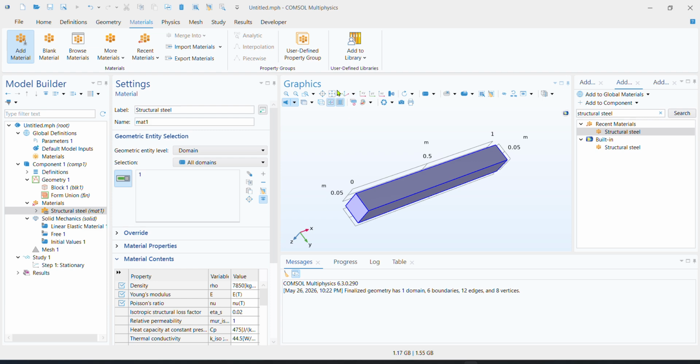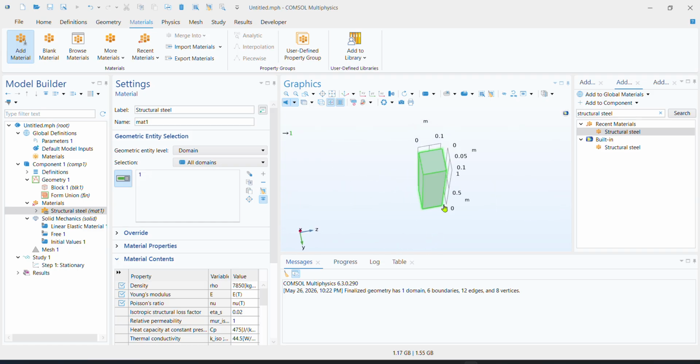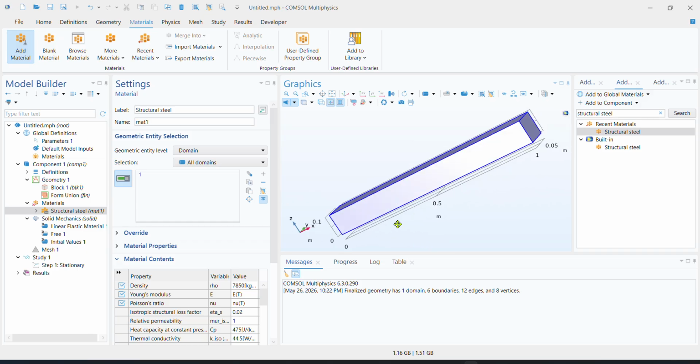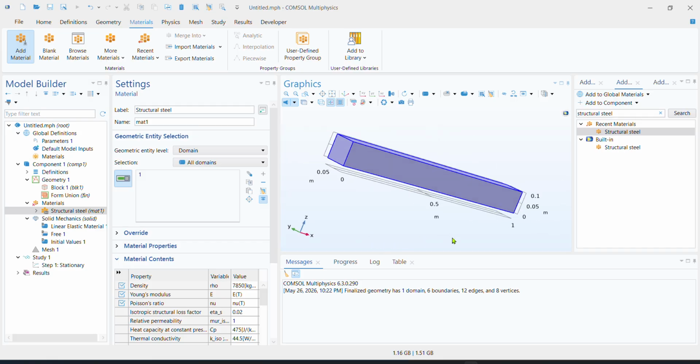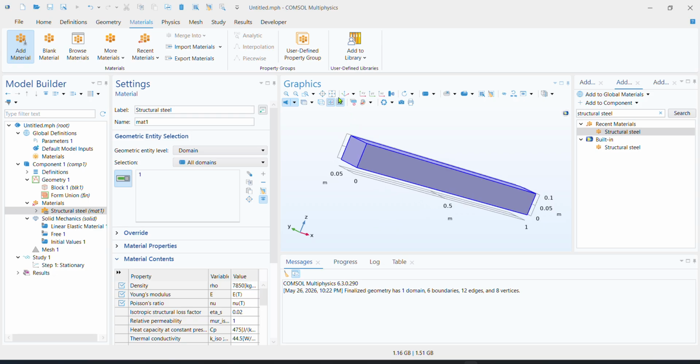You can also try to remember this one button here. I think it's really convenient because imagine you go to a very random view and you're not able to navigate back to your window. If this ever happens, if you press the default view button over here, it goes to that default isometric view, which is really convenient whenever I use Comsol. And by the way, clicking your left mouse button helps you rotate your view, and clicking the right button helps you pan your view. So these are interesting options.